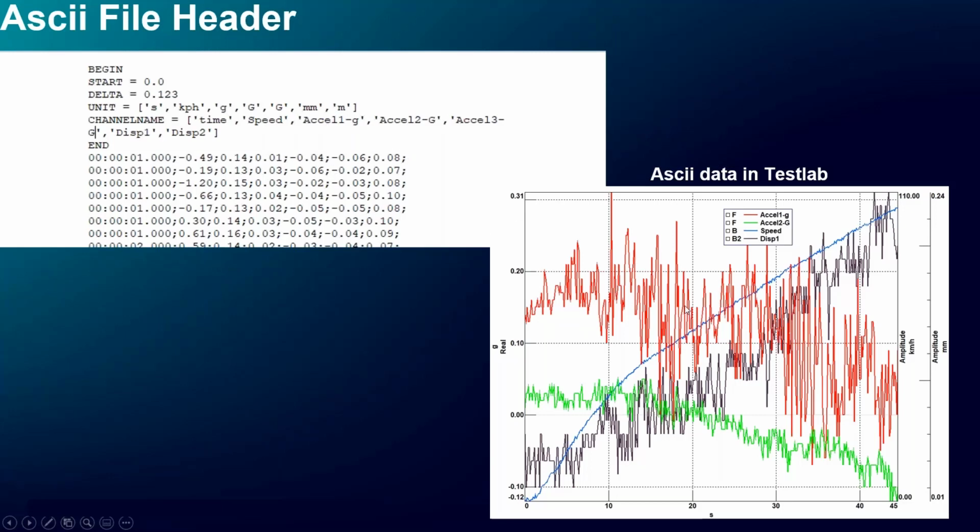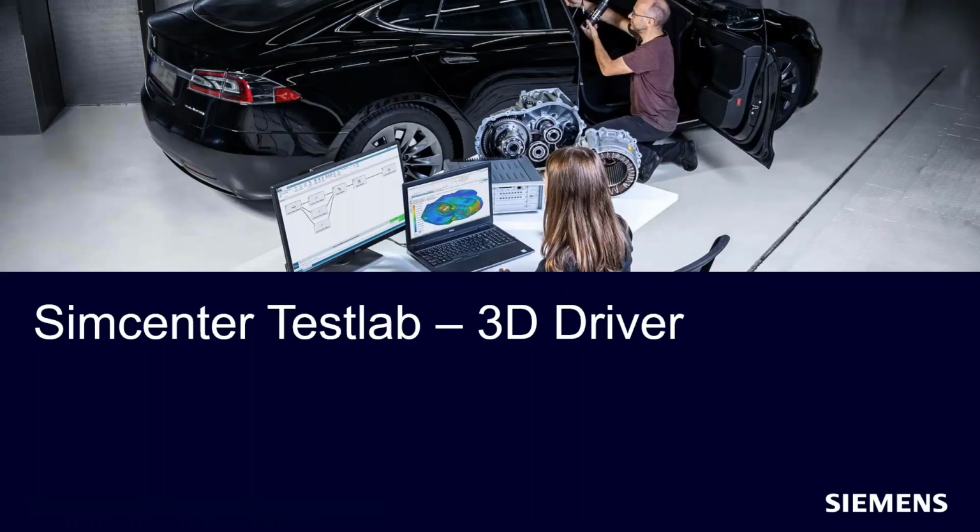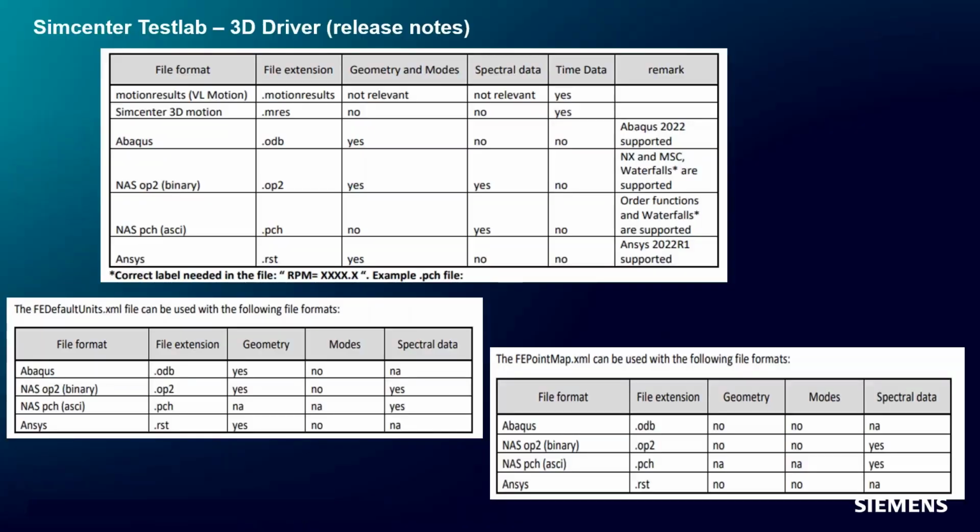If you want to do some frequency domain calculations, like calculating a spectrum or looking at tone to noise ratio and things like that, all that can be done with that data. As I said previously, we have this additional install that can be done on top of the TestLab install, and that is called the SimCenter TestLab 3D driver. This driver allows more in-depth analysis for certain file formats.